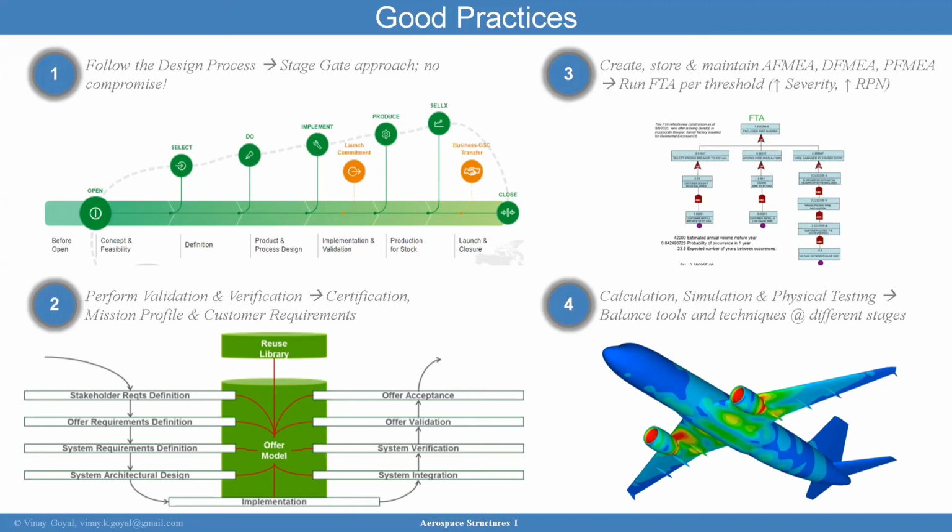Each one of these documents will tell you really what can go wrong with your product or your system. The FMEA captures three very relevant parameters: the severity, the occurrence, and the detection. So every single thing that you consider can go wrong from the user perspective, right, which is the application, will have to be stored in there. And this is where you will commonly find things associated to misuse, right? And the misuse can range from a person that didn't really read the user manual or the instruction, or they are completely giving the product or the system a different application from what it was intended to be.